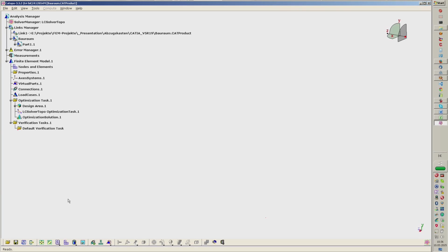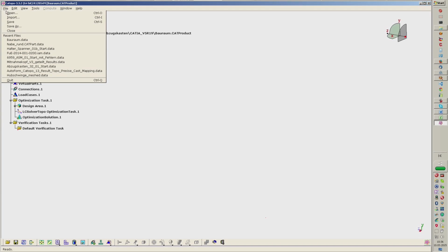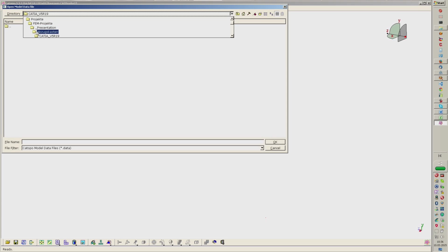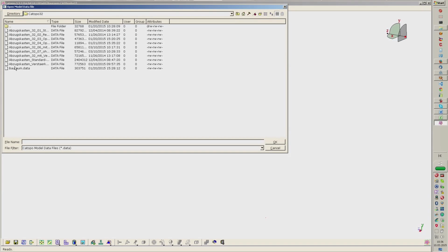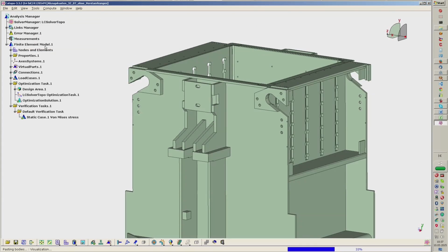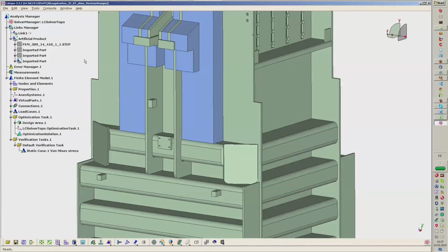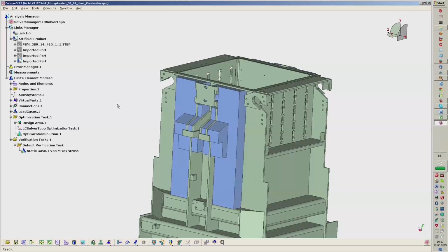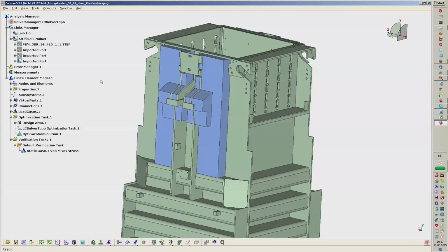For that, we model the design space first. That's the total area where we can place stiffness on. And this additional volume we add to our existing structure. We make a fine mesh on it, and now we had to define how we want to optimize it.